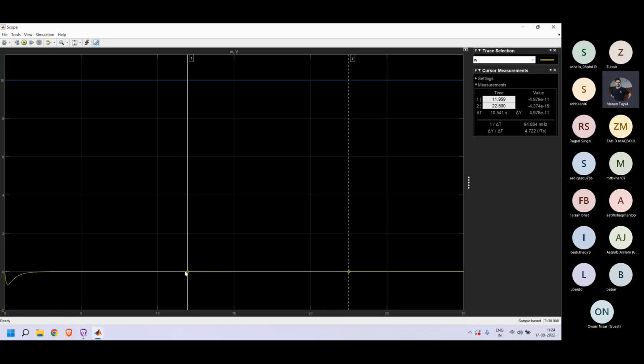Either I have to find ways to change some values, but generally we cannot change the motor values once we already have a motor. So all we can do is either reduce the external load torque, or increase the voltage, depending on the applicable motor voltage values that we can apply.